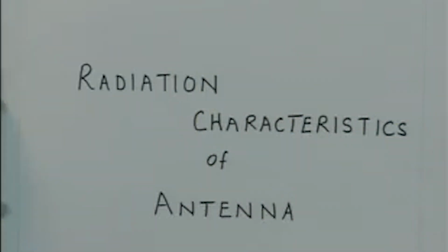At the moment we have a radiation pattern which is a very elaborate description, a 3-dimensional surface, and it is very difficult to really compare one antenna with respect to another quantitatively. Looking at the radiation pattern, we can always say this antenna has a certain direction for maximum radiation or certain directions for nulls, but what we are looking for is some quantitative measure on the basis of which the antennas can be compared. And that is what essentially we discuss in today's lecture. We discuss what is called the general radiation characteristics of an antenna.